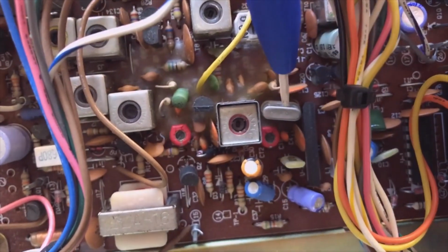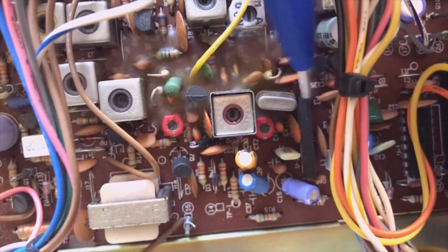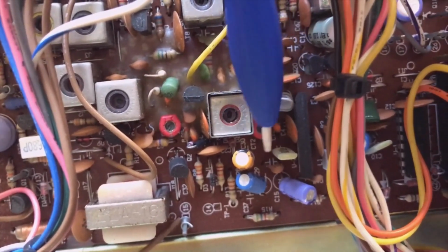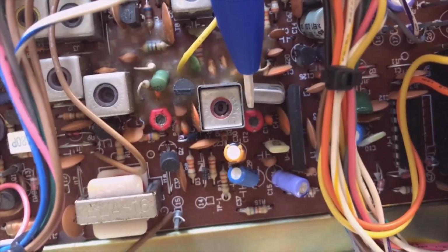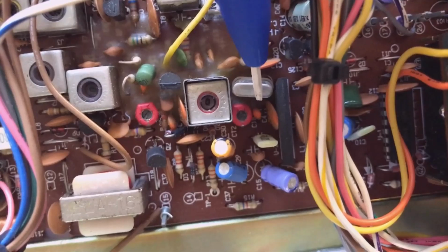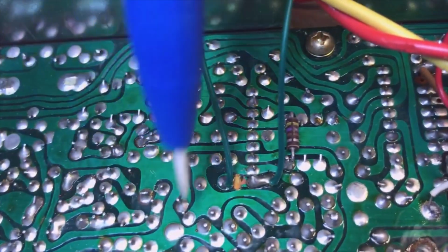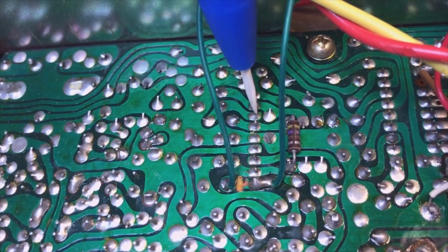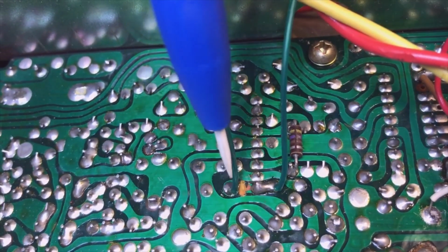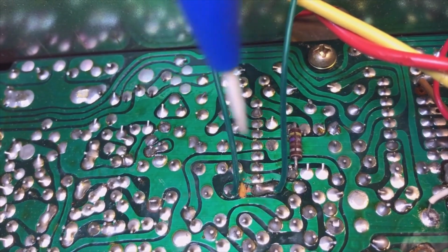Here we have the crystal, and here we have the IC it is connected to, and on the other leg is this trimmer. We need this for our normal channels. So if we cut the trace between this one and this one, then we are okay. How does that look on the other side? That is done here. As you can see, this is the strip, that is our black IC. We cut this, and we have the wire here.